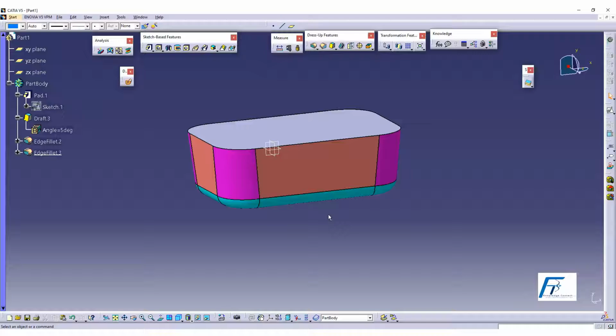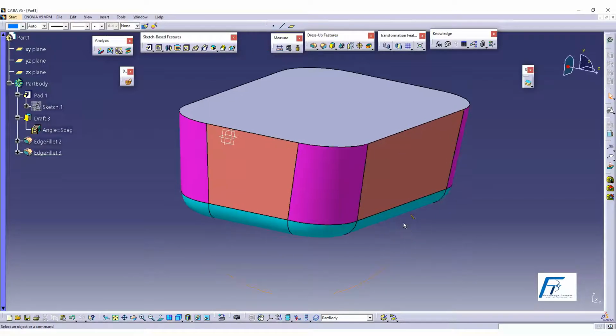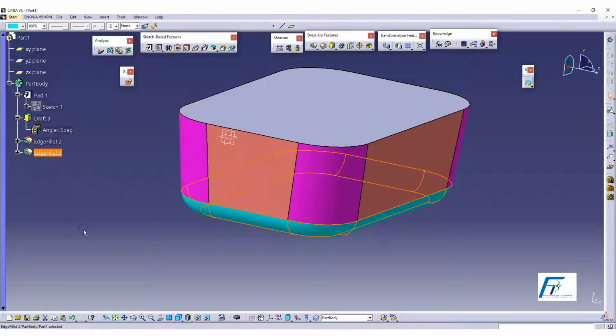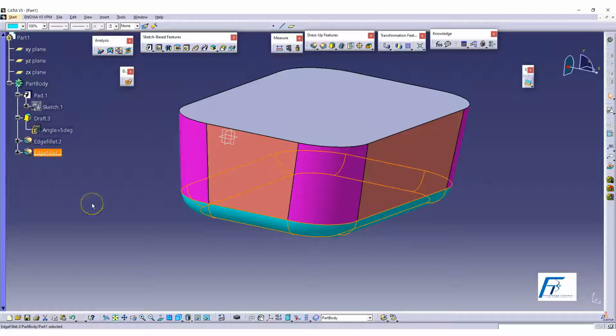At any point of time, if you reorder any of the feature, you will have adverse changes. The design itself gets collapsed. That means the first fundamental thing you need to understand is that always start with a pad, draft it, then give it vertical edges, then follow it. So out of these 25 people attending, I'm setting a standard in the industry that a 26th person who is not at all within this training group, I will tell him to go and change the parameter for horizontal edges. He comes exactly to this one and understands that this is horizontal. Because I set a standard.